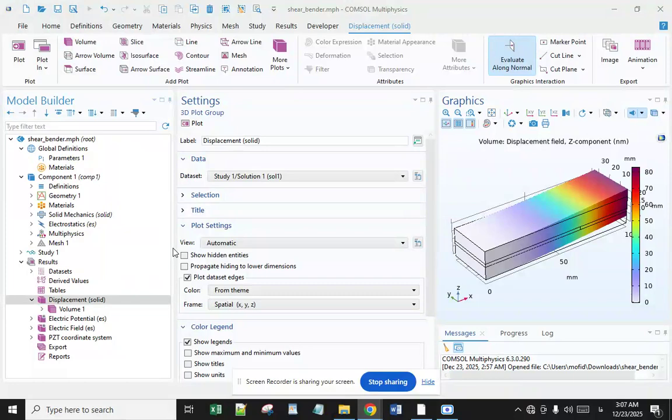What about the static analysis? The segmented geometric configuration of both actuation mechanisms is presented in this simulation and this figure, with L equal to 10 millimeters, H equal to 60 millimeters, and T is 1 millimeter. Length and position of actuator are 10 millimeters and DC is 15 millimeters unless stated differently. Beams are clamped at x equal to 0 and free at x equal to L.